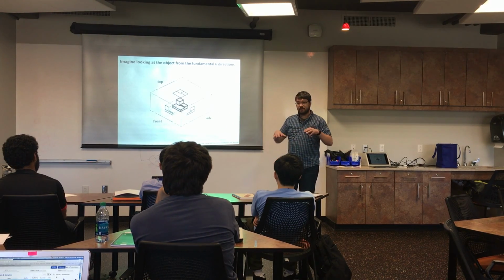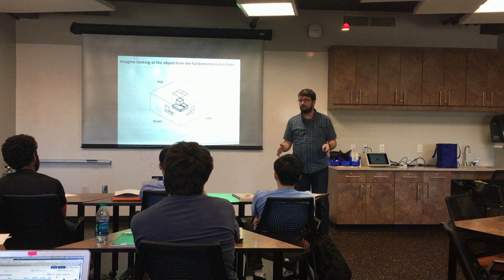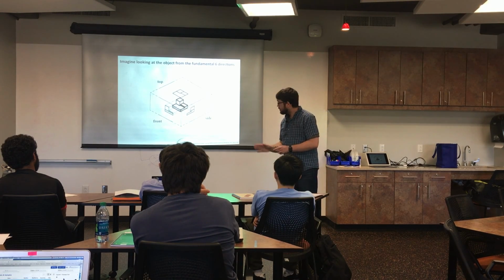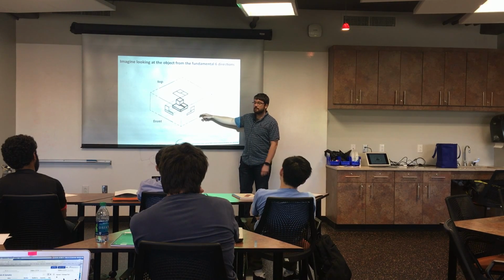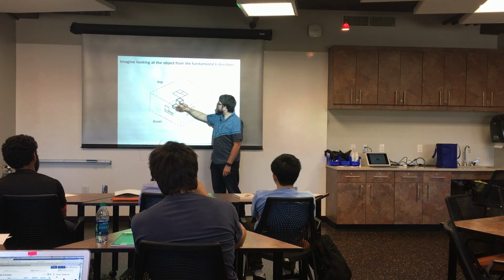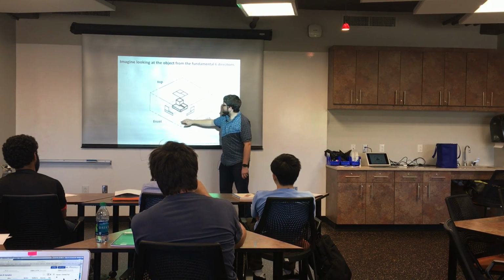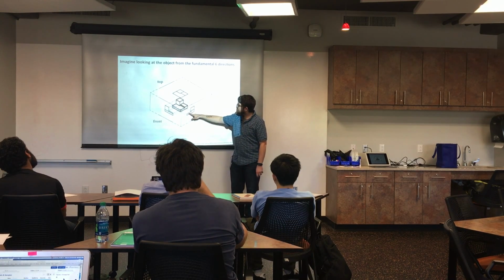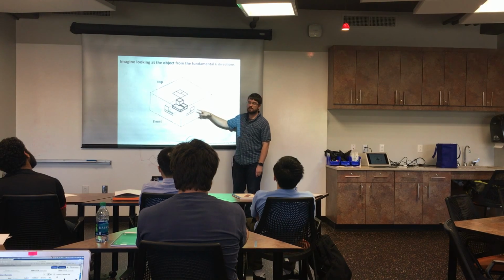But if you think about having a cube around this, so imagine building a plexiglass box and setting it over your part. And you're going to look down or in from each side, and you're going to trace exactly what you see. So from the top, we see the outside, there's the step, and there's this part that's jutting up, but it's just in 2D. And on the front, there's the part that's coming up, there's the step, there's the base. And on the side, we see the base, the step, and then the part that's coming up.